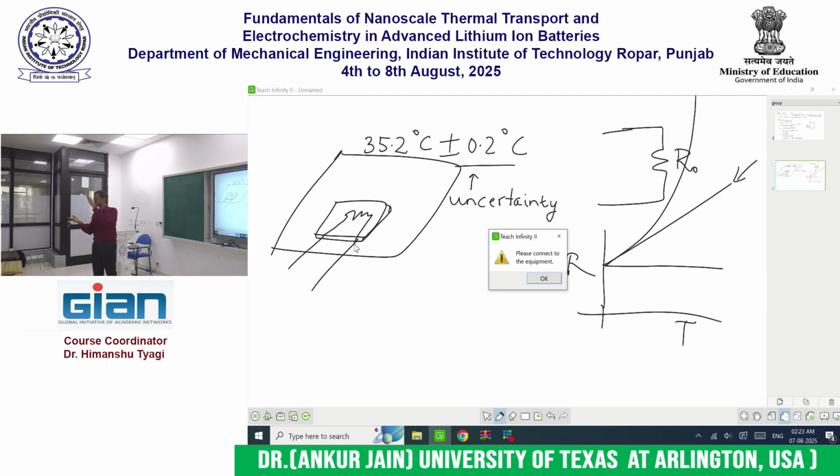Do I just put it there and press it with my fingers? Or do I put some epoxy between them and attach it? Thermally conducting, but electrically non-conducting. Exactly. So you can't use a metal paste or whatever which will short things around, right? Then what do I do?